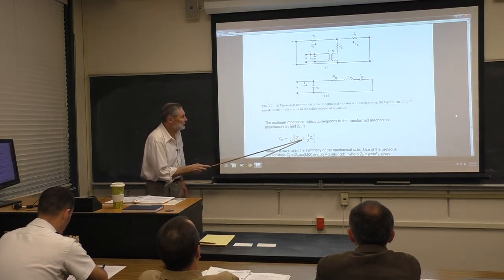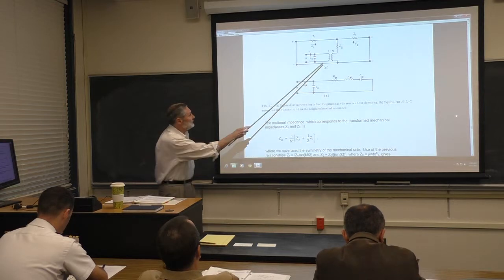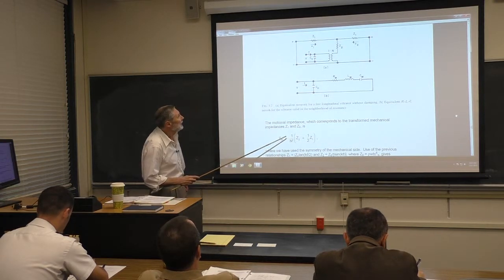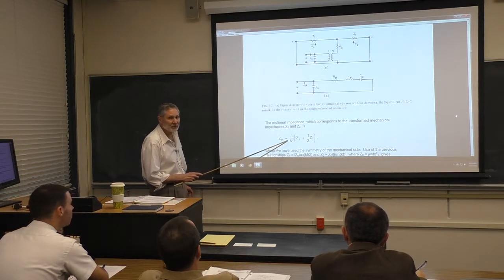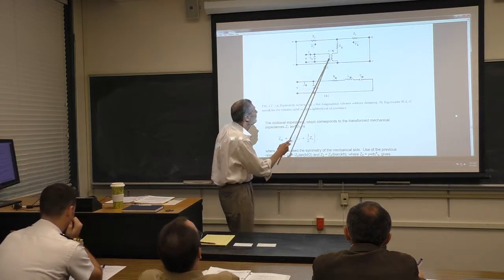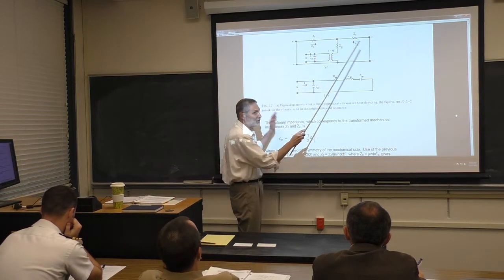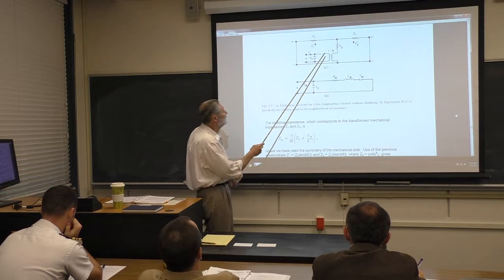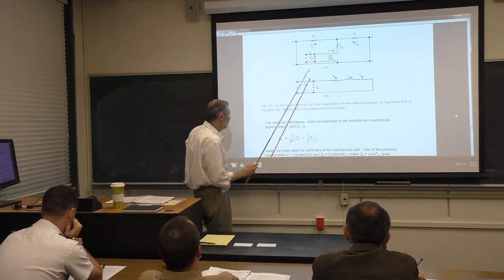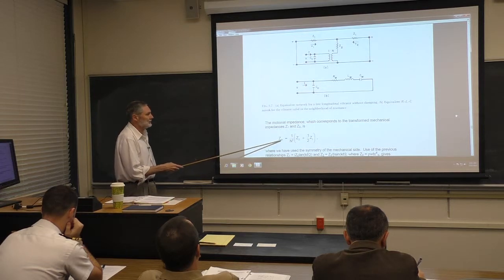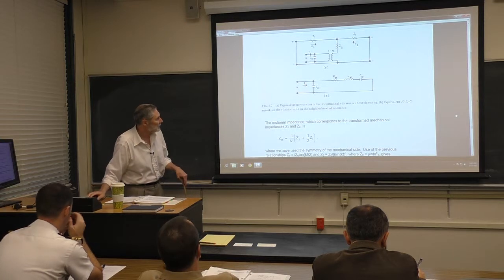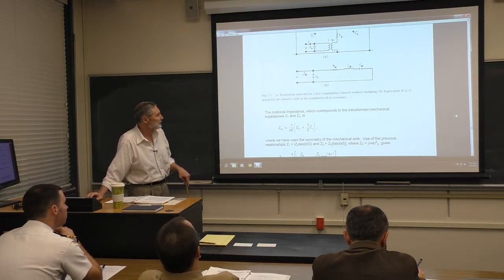So the equivalent impedance there is going to be 1/2, and then it's in series with this. And why is this here? You should be used to this by now. We've removed the transformer. Removing the transformer makes these elements fully an electrical circuit now. These have electrical values. So here's the motional impedance. But remember, it's a capital M, so it's electrical. Okay, so that's exact, right?